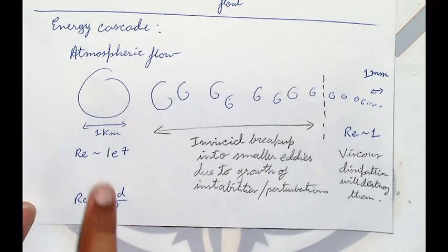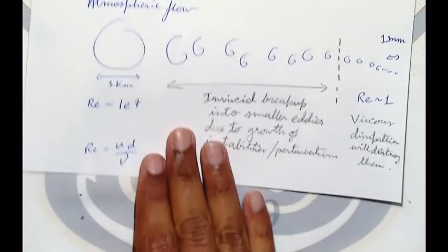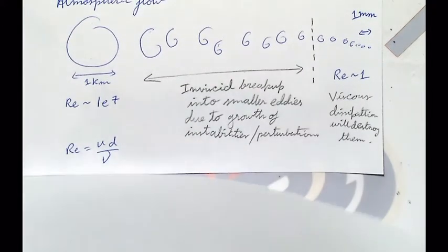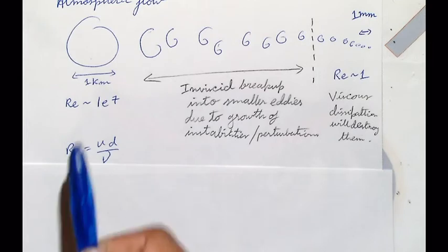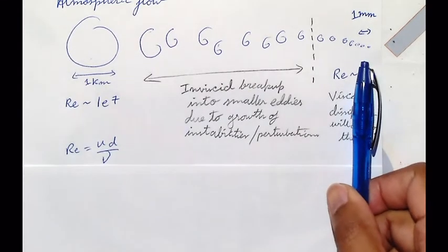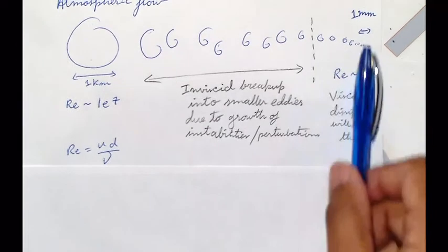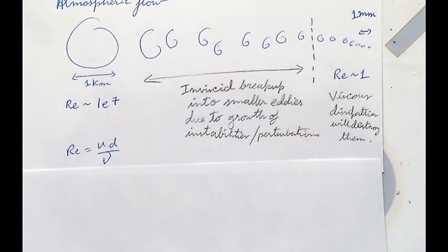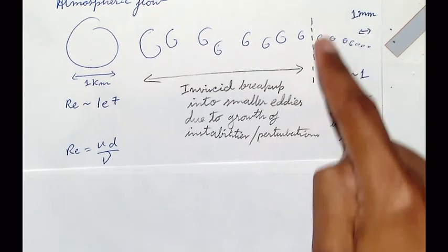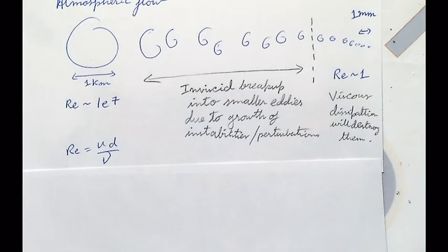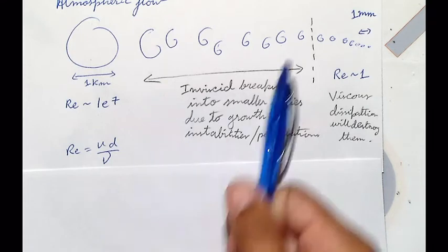So what is the scale separation we're talking about here? Physically, do you agree that all the length scales starting from here to here are important? Think about what will happen if we get rid of these. What will happen if these did not exist? Small eddies with Reynolds number more or less 1. Medium eddies would just continue their momentum? Yeah, the medium eddies would just keep existing.